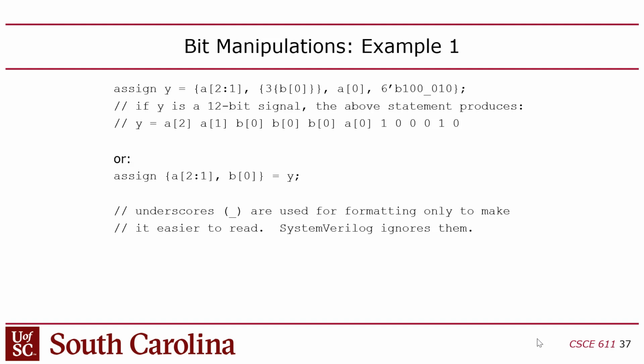So if you say addi in RISC-V, you only got 12 bits to put the immediate. Of course, you can combine it with another instruction if you want more bits, but in one instruction, you can only have a 12-bit immediate. That 12-bit immediate, if it's used in the context of a signed operation like add, is going to have to be sign extended to 32 bits, and the way you do that sign extend is you duplicate the sign bit 20 times. 20 sign bits and 12 immediate bits. You guys with me? So that's a common use of that duplication thing.